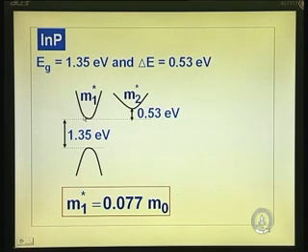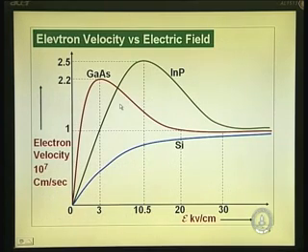Now, the effective mass here is not as low as that of gallium arsenide, but slightly higher, 0.077. That gives the mobility of electrons in indium phosphide slightly lower than that of gallium arsenide, about 4,500 or so. So, this is smaller, or around 5,000. Okay. So, here this is almost comparable. Now, let us see what happens because of that.